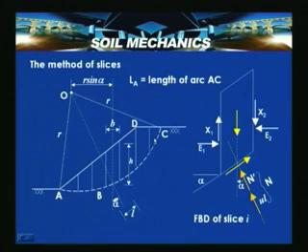Now, if I take the free body diagram of the ith slice and represent it here, it shows the various forces which can act on the slice. Here this is the slice, having weight W. If W consists of a number of soils, like soil 1, soil 2, soil 3, soil 4, the compound weight can be found very easily in this method.